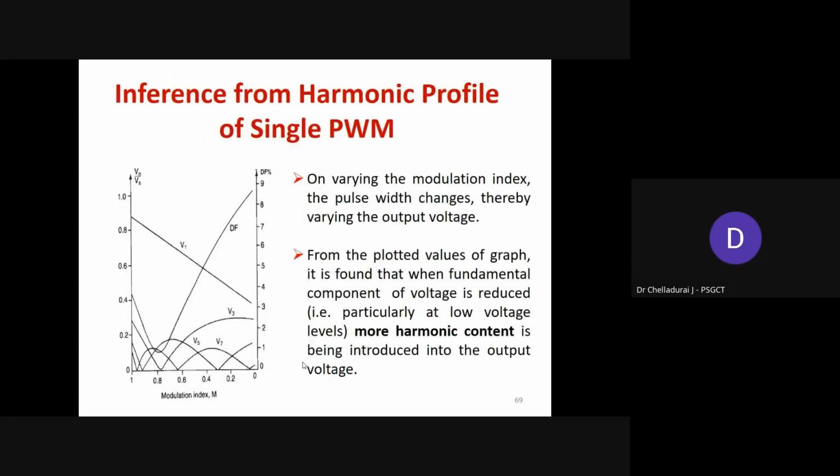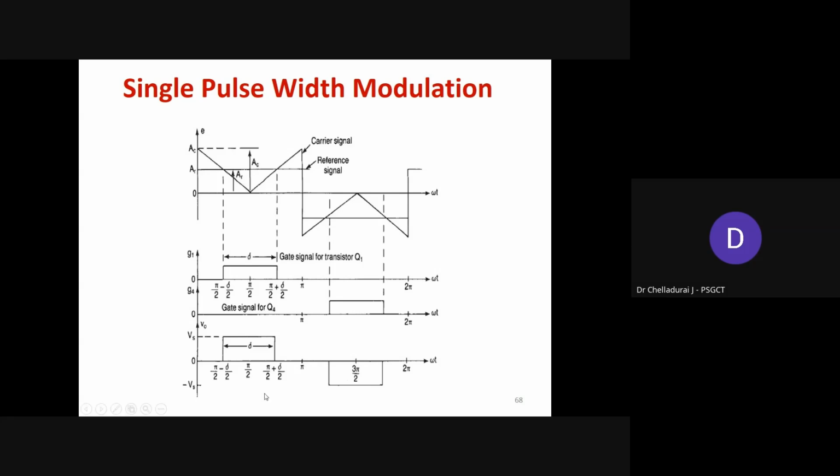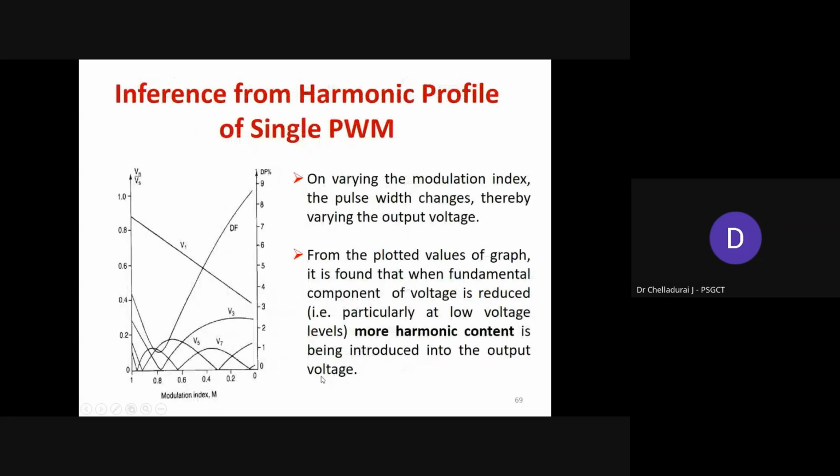Now the advantage of using this. We already discussed that one of the very important performance parameters for any voltage source converter is harmonics. This simple quasi square wave output normally contains very high lower order harmonic components. Here the modulation index is one of the very important performance parameters, especially in PWM techniques.